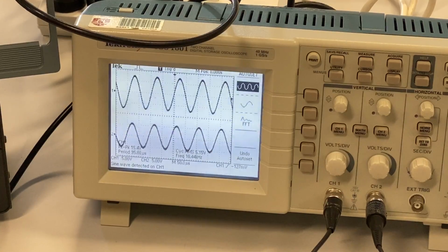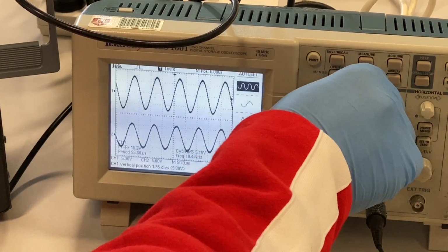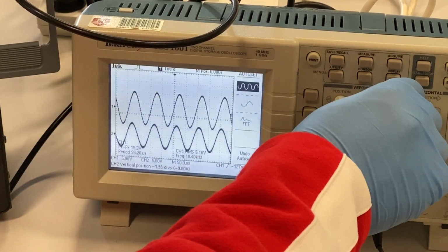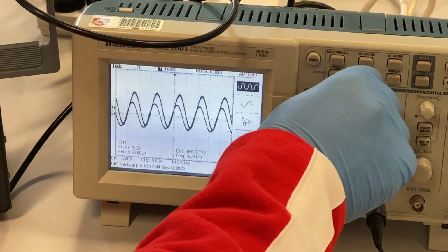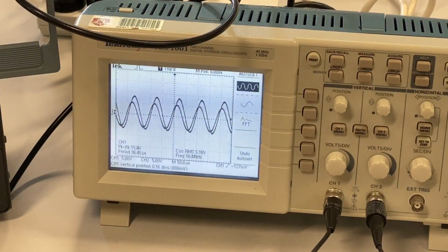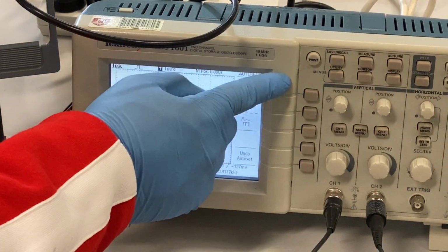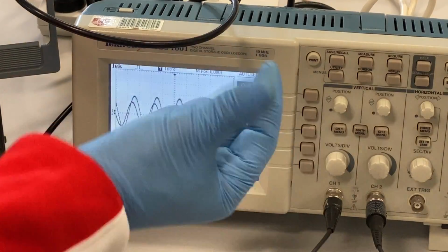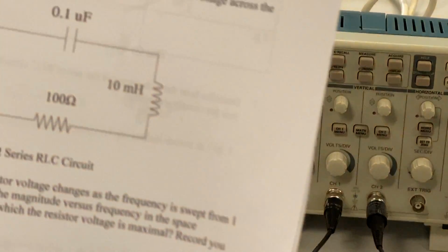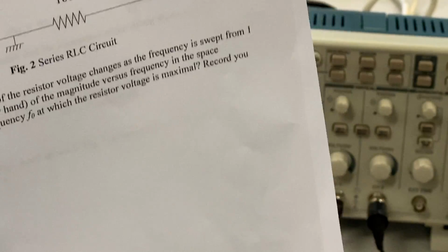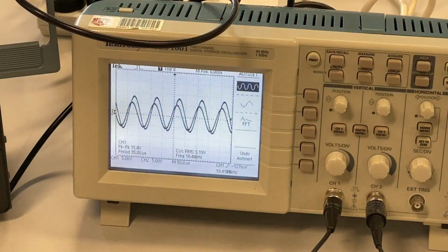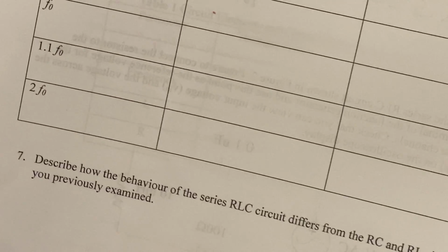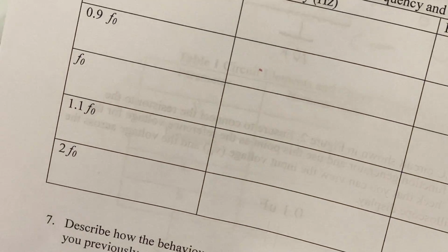Right? Now, what you're supposed to do at that point is measure the relationship between the phase shift, which is where you use those two cursors. You just take amplitude, time cursors, use two time cursors, use this formula that I applied here, then plot a graph. That's it. Okay?